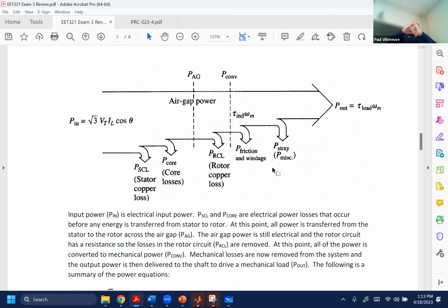That generator wants to spin at synchronous speed, so 1800 RPM, but I'm continuing to put more energy in. How do I keep that turbine from overspinning? I want to go higher than 1800 RPM, but the induced torque has to match the applied torque. That's when you don't continue to increase in speed.